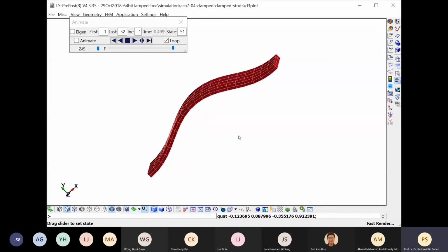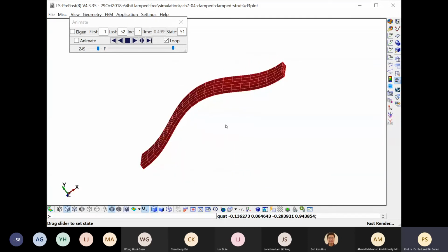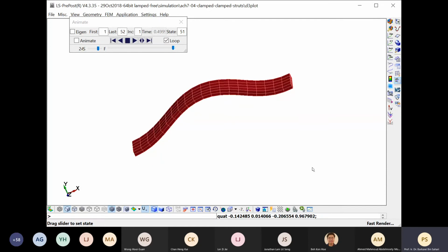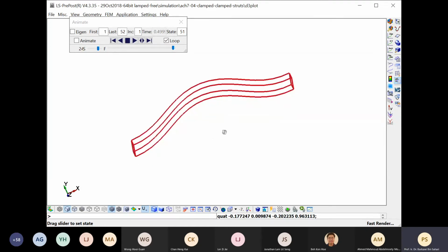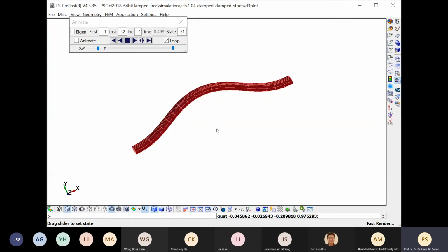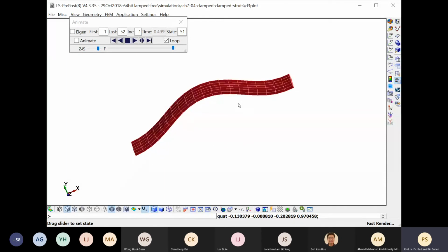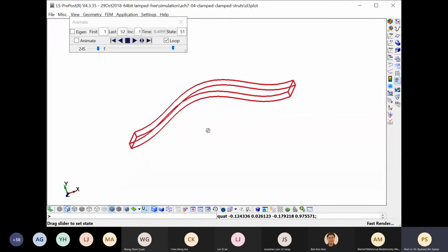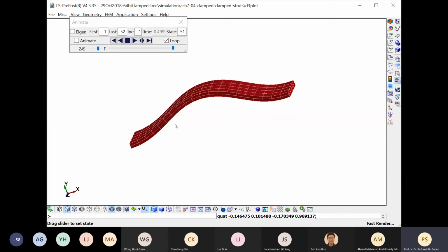Actually, we have not solved it, so we want to use the effective length approach in the solution for the clamp side. Now the effective length is the location of 2 points on the beam where the bending moment is 0. So on this particular work, we'll find where the bending moment is 0 and where sigma x is 0.